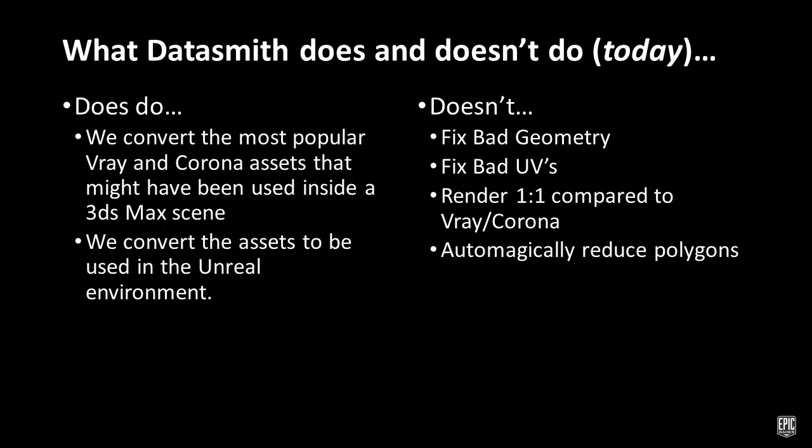Another thing to be aware of is that Datasmith doesn't automatically reduce polygon counts. Whether you're in CAD or you're working with a huge data set, you may be concerned about engine performance, and one solution is to reduce polygons. You'll either need to do that in 3ds Max or your CAD application, or you can do it in Unreal Engine using the LOD tools, which are excellent, but Datasmith won't automatically reduce those polygons upon import.